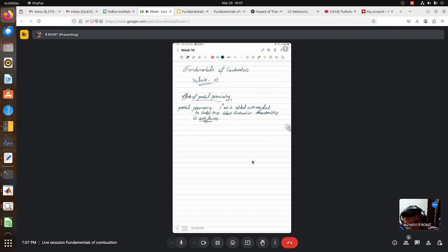In order to reduce the sooty flames, when you are having 0% of air, only fuel is going, you will see a sooty flame where you are having your tip being opened up, producing a lot of soot. But once you introduce more and more air, you will see that your flame gets closed and you don't have that smoky thing coming up.